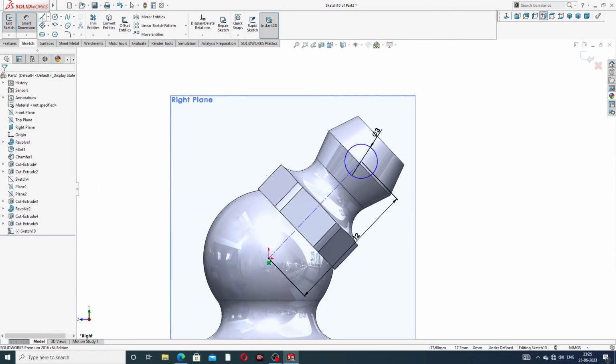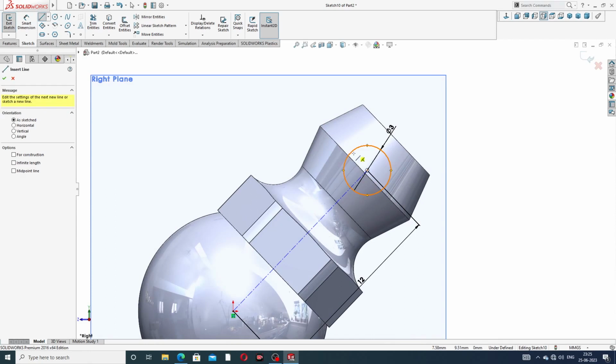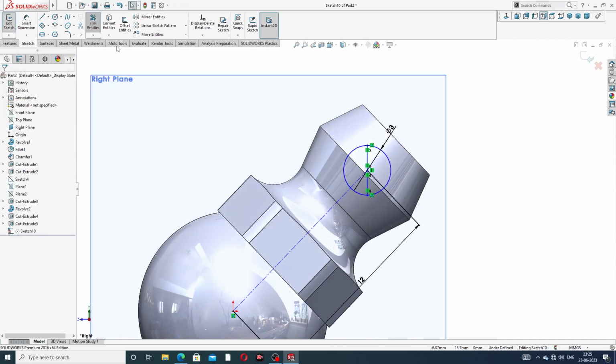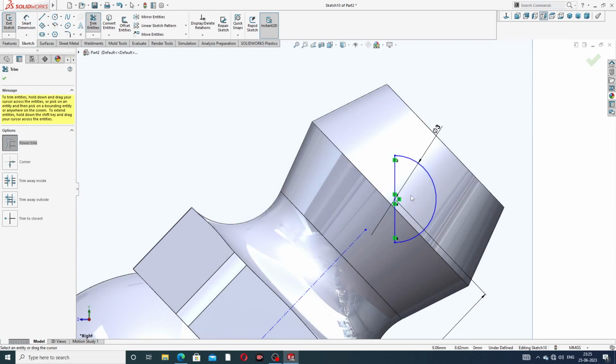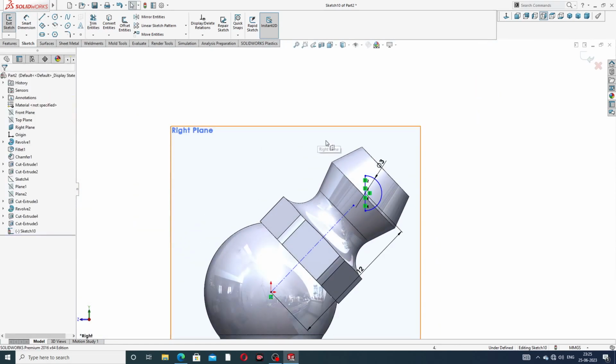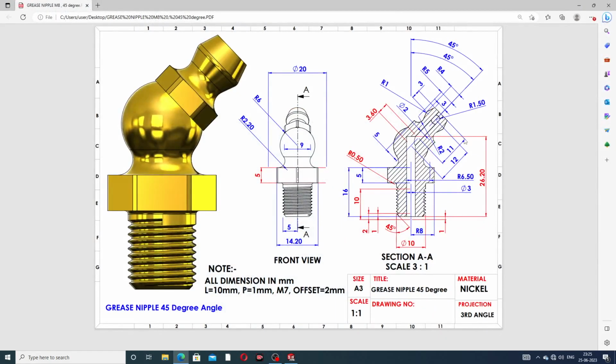and this line is this, and some extra portion is cut here. Okay, and guys, this is very important. Use a 3 cutout, 3 dia, and this circle, diameter is 3 millimeter, radius is 1.5 millimeter, and distance is 12 millimeter.